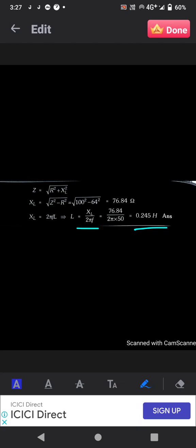First we calculated the power factor, and from the power factor we can calculate the inductance and resistance. How we solved: these formulas are very important. They are simple formulas. What we have to remember is only the impedance triangle. From the impedance triangle we can calculate resistance, reactance, and inductance also, if they give the power.